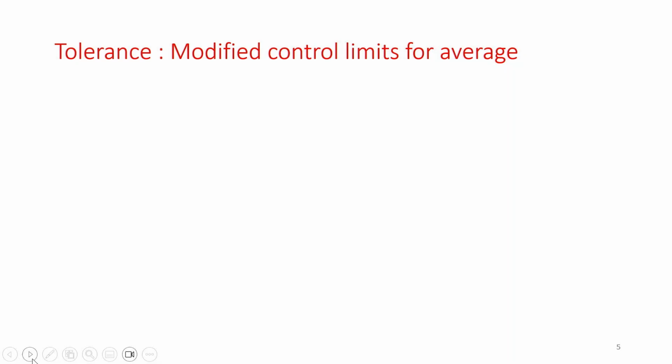That is how we can make a chart for range. And if we see the points are close to the center line, the closer they are, the better it is, then the variability will be less. And the further they are from the center line, the variability is more. But variability will always be there because of random variations in the process, some of these causes of random variation we are not in a position, or we may not be able to completely get rid of them.